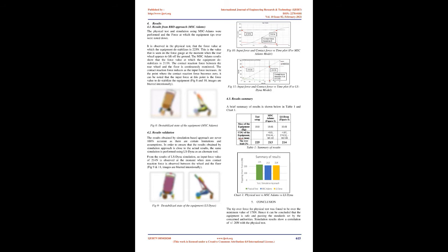FE analysis approach. The following procedure is followed for FE analysis. HyperMesh is used for pre-processing and LS-DYNA is used for solving and post-processing. All the plastic parts are modeled as solid tetrahedron, and all metal frames are modeled as shell mesh. All the parts are assigned with MAT20, rigid material, i.e. the material does not undergo any deformation under load application.